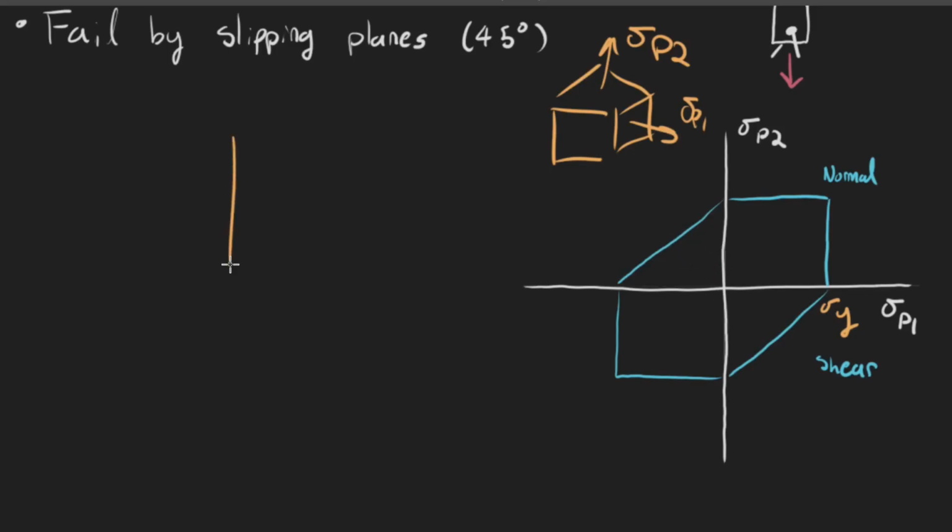If you imagine our shear, normal stress Mohr circle that we were talking about, if they're both positive and one of these goes above the maximum, or if one is positive and one is negative but the difference between them is greater than the maximum, then we say there's failure. Basically, any point on these axes represents a stress state, and if I'm outside of this shape, then I'm going to have failure.